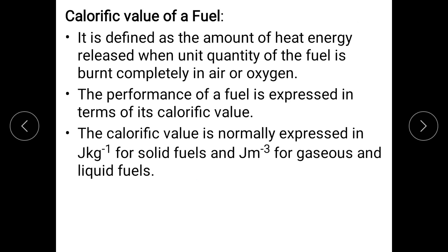Performance of the fuel is expressed in terms of the calorific value. If the fuel releases more energy when unit quantity of the fuel is burnt, then that fuel is considered to perform well. Its burning efficiency is considered to be good. The calorific value is normally expressed in joules per kg for solid fuels. When 1 kg of the fuel is burnt, how much energy is released in joules? For gaseous and liquid fuels, it is expressed in joules per meter cube.